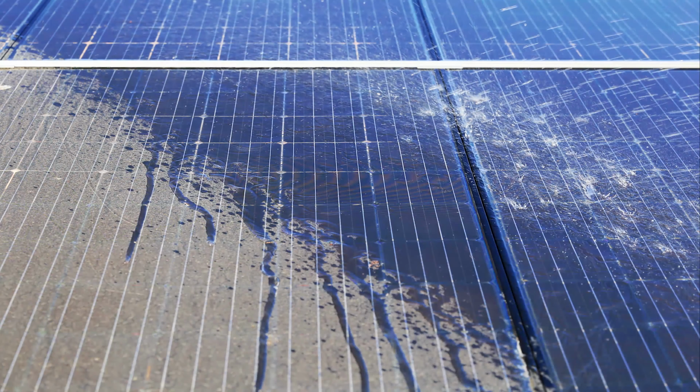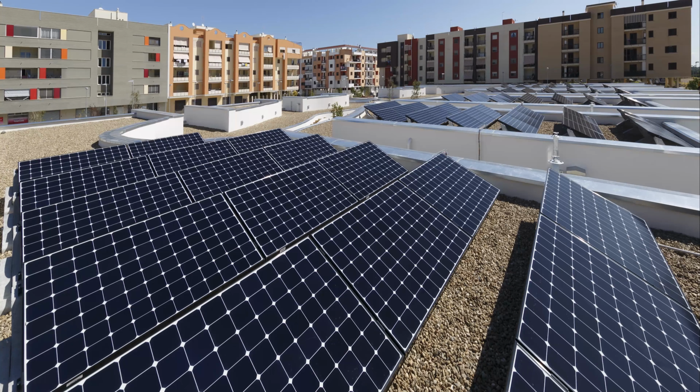When it comes to working out the best angle for a system on a flat roof, you have to consider both the azimuth and the pitch of the array. If the pitch is quite steep, it's more important that the array is accurately aligned to south. On the other hand, if the modules are flat, north or south become irrelevant. In practice, you wouldn't want your modules completely flat, because they would build up a lot of dirt and residue from dust and rain. But systems with a shallow pitch are quite popular, because you can pack more modules into a given space. What we really care about is how much energy the system is going to generate over a given time, usually a whole year.